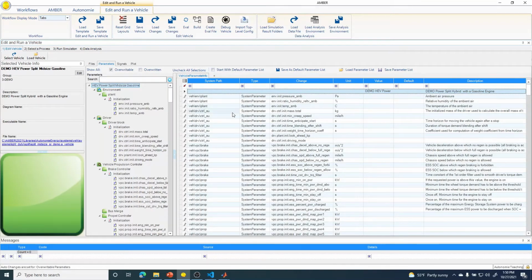And again, the overwritable parameters are all the parameters that are marked as overwritable in the M files and the preprocessing files. So those checkboxes that you would check in the metadata editor to enable overwriting, if any of those parameters have their checkbox checked, they appear in this table. And you'll see that the values don't appear for all the overwritable values. It's because they're not yet in the workspace. So if I click eval, it will evaluate and then load all those default parameters.